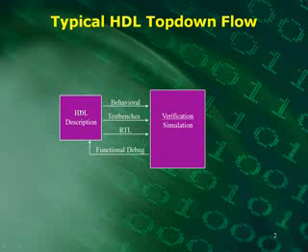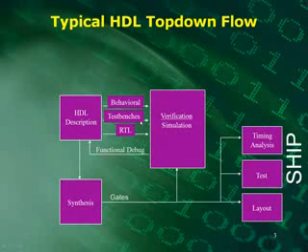Here we've written our HDL, hardware design language descriptions, and we've either written them in behavioral models or RTL, maybe we've written test benches, and we want to run those through some sort of verification simulation like I was showing you just now. If we find problems, we go back and debug, then simulate again and keep doing that, and that's what we call our functional debug.